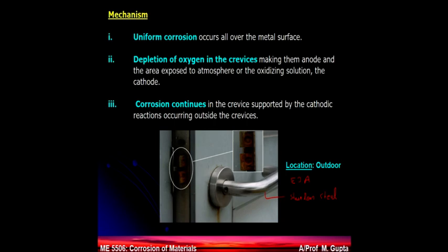It's quite all right. But if you look at this area here, which locks in, there's a cavity inside this part, where the part shown here goes inside when it's in the lock situation, and you see how much it is corroding. And since the rust is brown, it's a steel. So now you have this outside part of the handle which is not corroding in the same atmospheric condition, and the part which goes into this cavity, cavity number 1 here and cavity number 2 here inside, is corroding because it remains locked overnight every day. So for 12 hours it is locked at least.